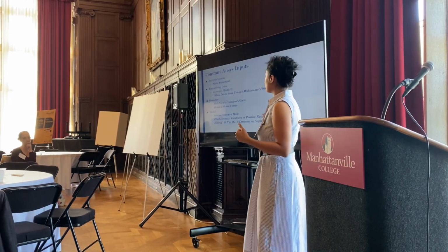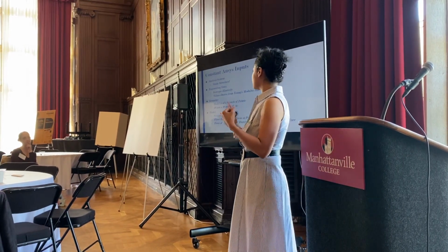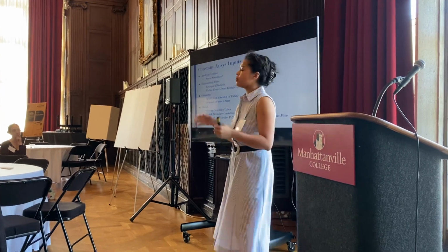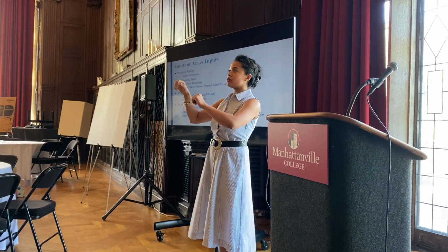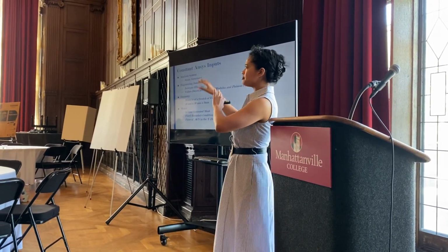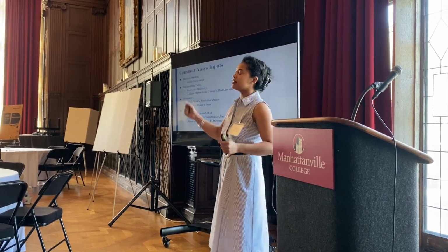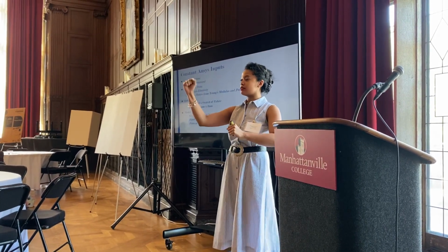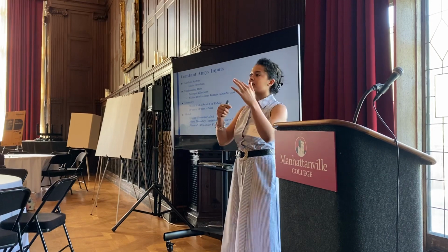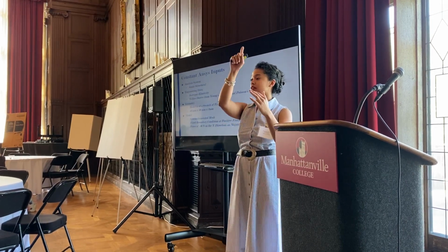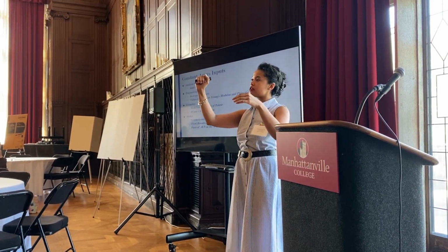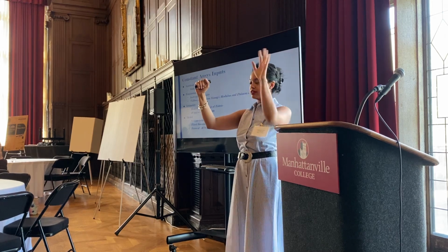Last but not least, for the model, we consistently used a system-generated mesh, and we had a fixed boundary condition on the positive facing z-axis side. So it was kind of like a side of the fabric was being held, and the other side of the fabric had a force of negative 50 newtons in the y direction. So it was being held on one side, and it moved up and down, okay?